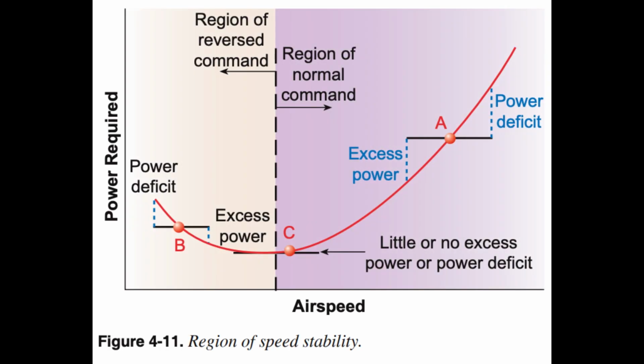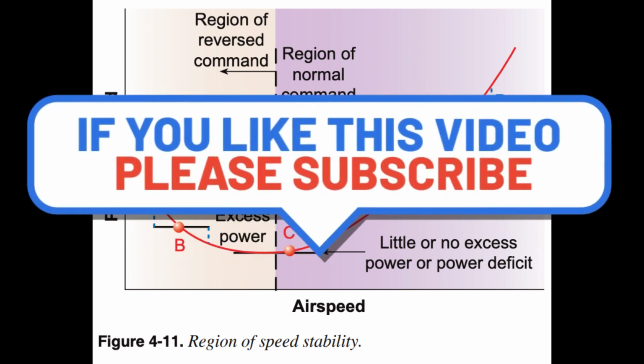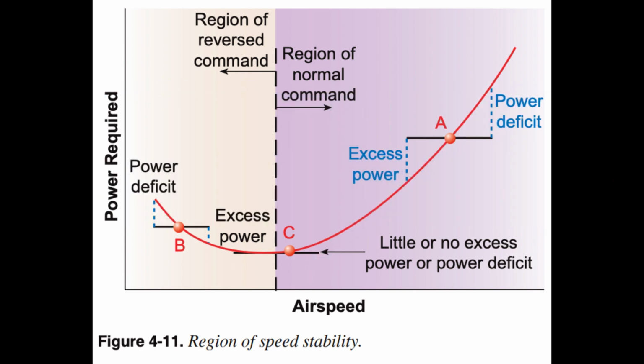Large airplanes. Pilots of larger airplanes with higher stall speeds may find the speed they maintain on the instrument approach is near 1.3 VSO, putting them near point C, figure 4.11, the entire time the airplane is on the final approach segment. In this case, precise speed control is necessary throughout the approach. It may be necessary to temporarily select excessive or deficient thrust in relation to the target thrust setting in order to quickly correct for airspeed deviations.